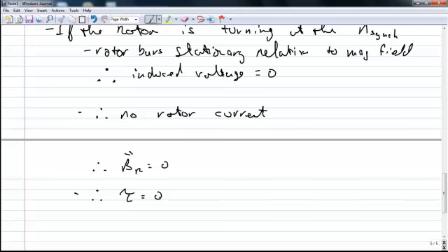As a result of this sequence of events, we can conclude that an induction motor can approach the synchronous speed, but it can't reach the synchronous speed. The reason it can't reach the synchronous speed is because there will always be some friction or losses to overcome. And at the synchronous speed, there would be no torque to overcome those losses, so it cannot reach that synchronous speed.